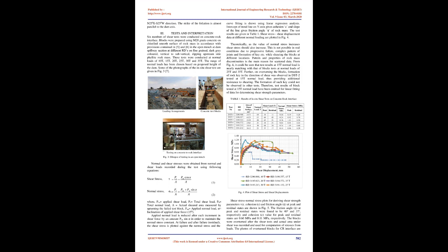These tests were conducted at normal loads of 10T, 15T, 20T, 25T, 30T, and 35T. The range of normal loads has been chosen based on proposed height of the dam. Some of the photographs of the in-situ shear test are given in Fig 3.7. Loading arrangements. Concrete test blocks. Testing on concrete to rock interface.